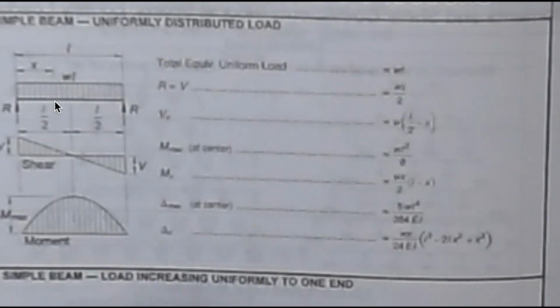Then all I do is take this equation, watch my units, and plug in my value of x. So at the support, that's x equals 0. Over here, it's x equals L. If I want the midspan, it's L over 2. I can choose any point and instantly get the equation of that elastic curve. That's very, very handy, and it saves you having to do all those classic structural analysis methodologies that we look at.